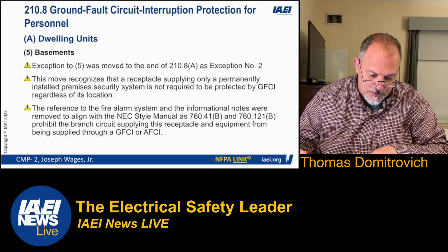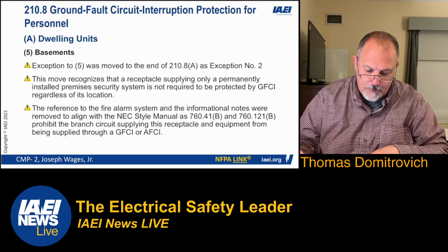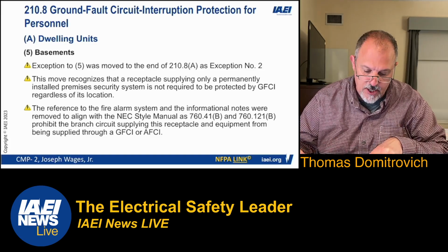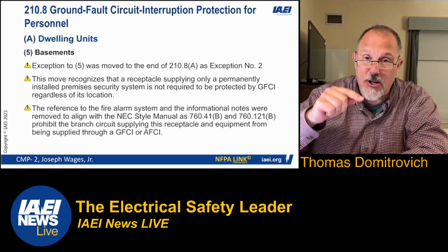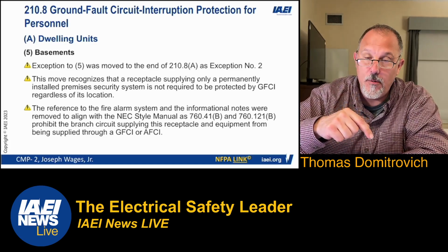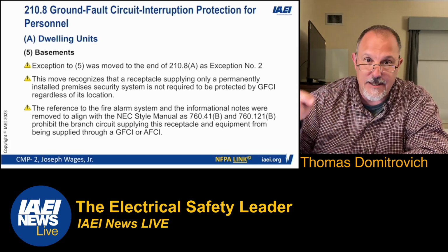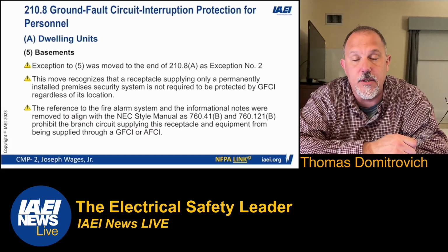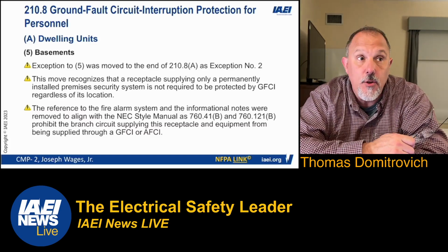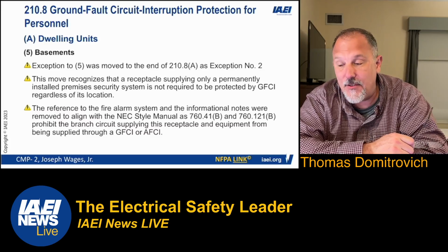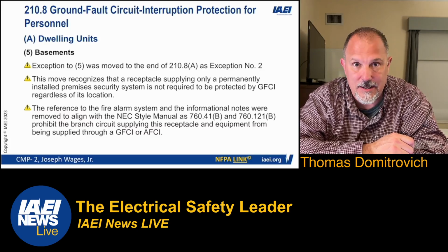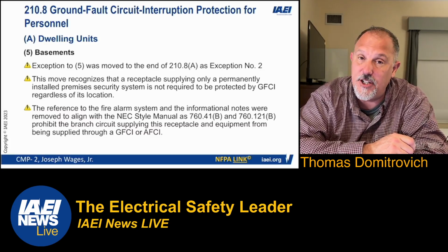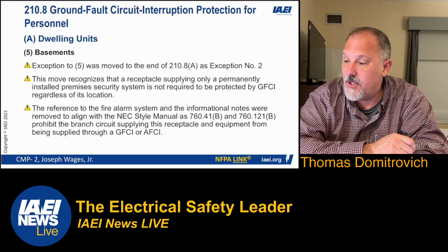So we made the exception say a receptacle supplying only a permanently installed premises security system shall be permitted to omit ground fault circuit interrupter protection, not required to, not a required exception. So on that security system, you can still put GFCI, but you can't on the fire alarm and signaling system because 760 says it shall not be on that GFCI. So that was the change we did.